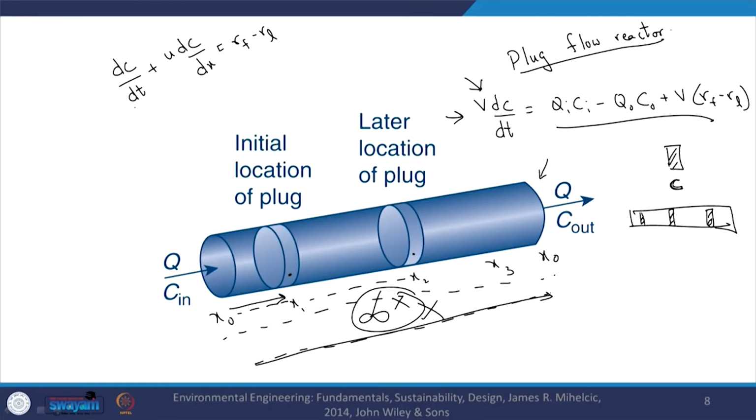But here as you see, you have concentration change with time, concentration change with distance and the rates of the different formation and loss reactions. So, if I want to apply it to this reactor, the plug flow reactor PFR, please note that these are all ideal case reactors. What can I do? I can directly apply this particular equation. So, if it is at steady state, what will it transform into? This particular term will be 0 and u dC by dx is equal to rate of formation minus rate of loss, right.